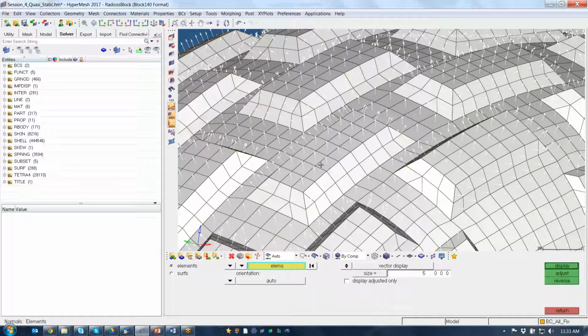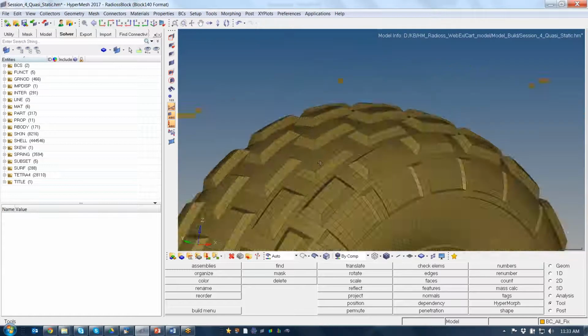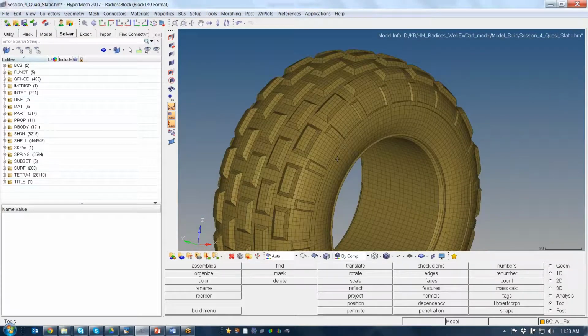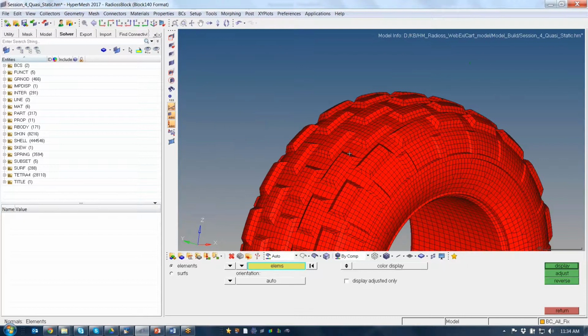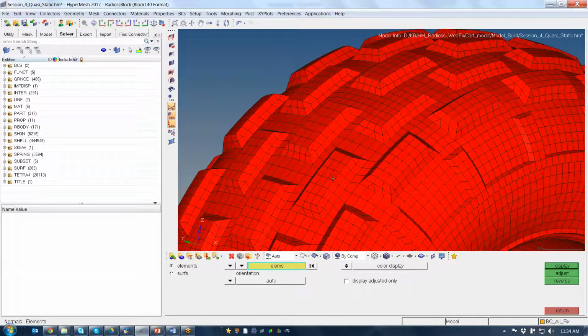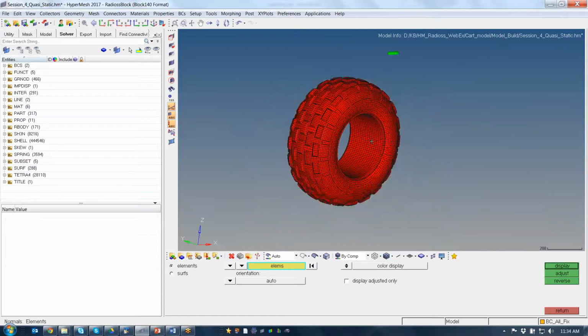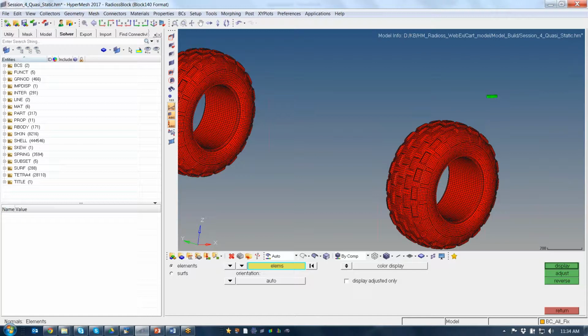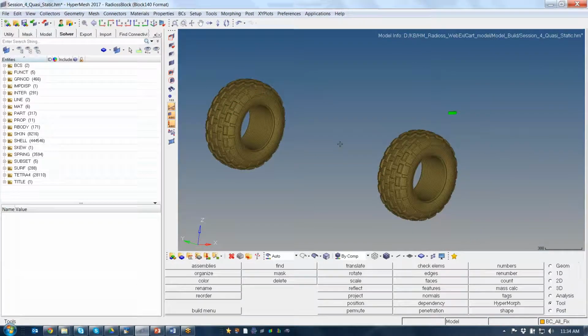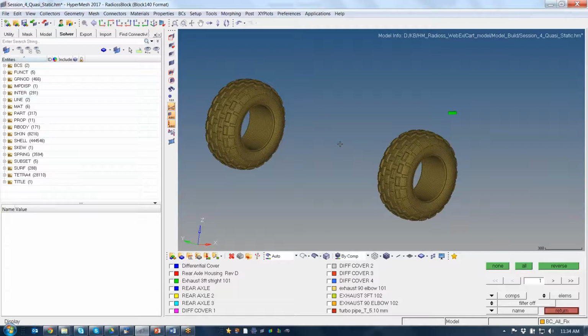The other easier option: outward normal is displayed in red, so I have to ensure that all of this is one color. Yes, we saw this was outward and that is showing red. All the elements should be the same. Otherwise, we can change the orientation and make it outward. As of now, all is good, all are facing outward. So these two are the prerequisites from the modeling perspective to create the monitor volume. That is fine.